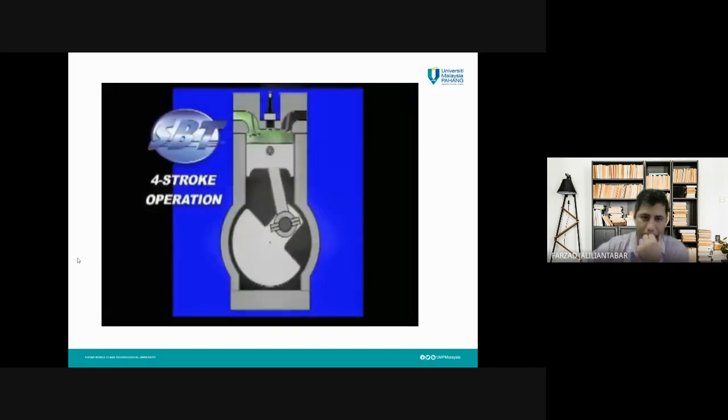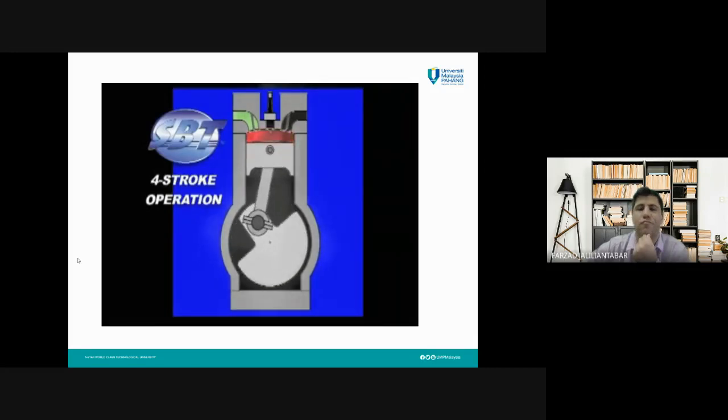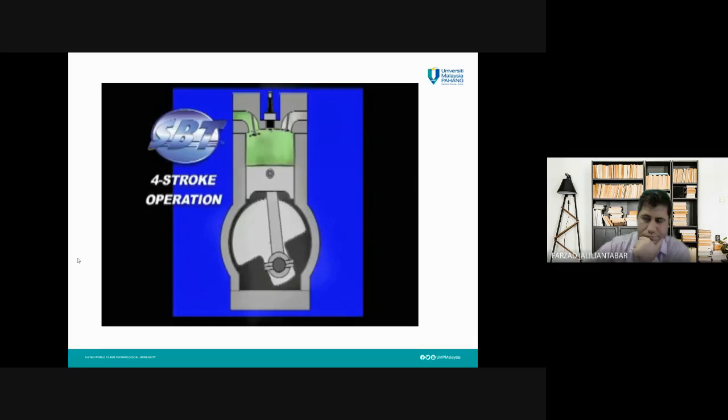The piston lowers for the intake stroke, drawing in the air-fuel mixture, raises for the compression stroke. The air-fuel mixture is ignited for the power stroke, forcing the piston down. And finally, raised for the exhaust stroke, forcing the exhaust out of the engine. The cycle then repeats over and over, turning the crankshaft, which is connected to the impeller, which drives the craft